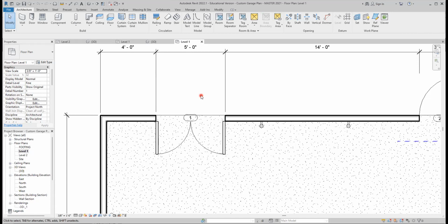Now, when you go to page A6, this is our door schedule. Again, this is all really simple, but this is what you would do if there were 600 doors in this project. You'd do it the same way, okay? So we're taking a look at this. Now, for door number 1, can you guys see that it says it's a door double glass, and it's 60 by 80 inches, okay? So this is 60 inches wide by 80 inches tall. That's what needs to go here.